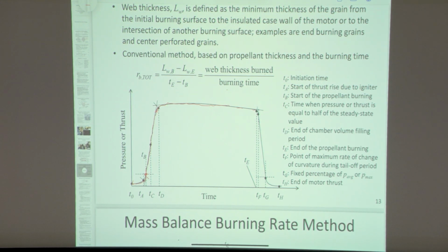And so right here at this point, I've reached the casing, there's no more propellant. And the pressure's still high and it slows down because there's still gas pressure inside the chamber, and that's got to be released through the nozzle. And that's what you're seeing here then.